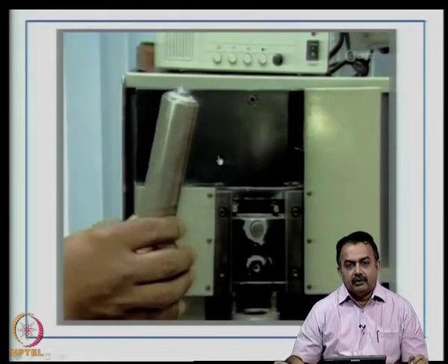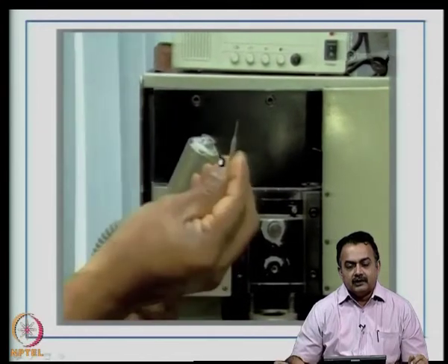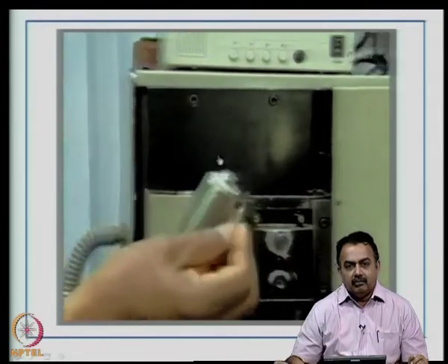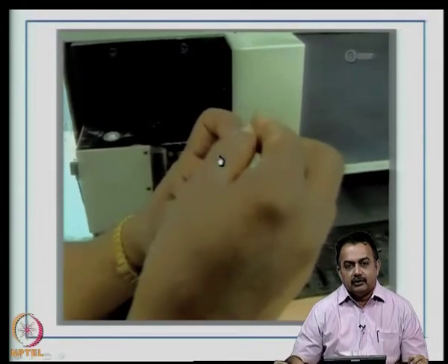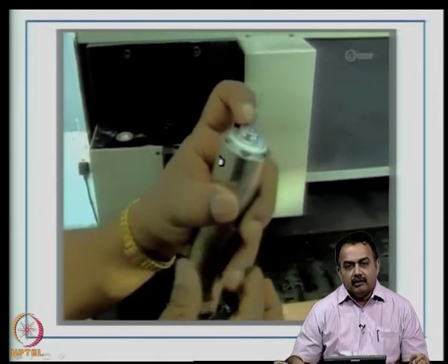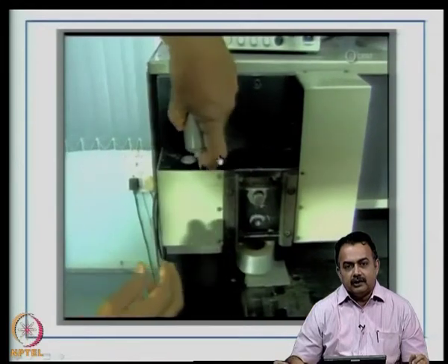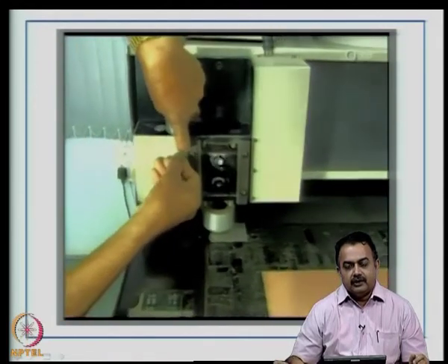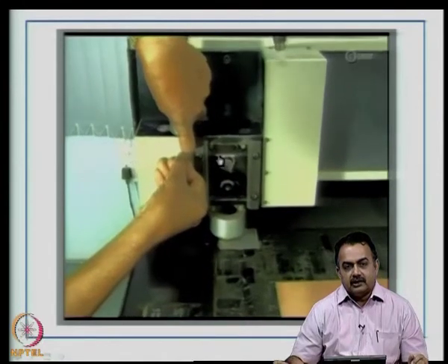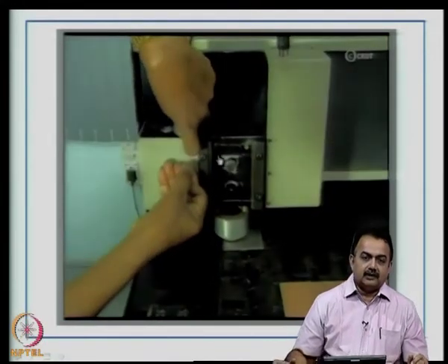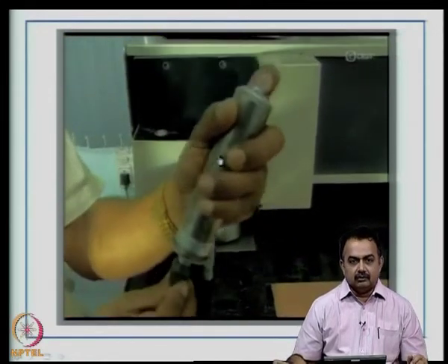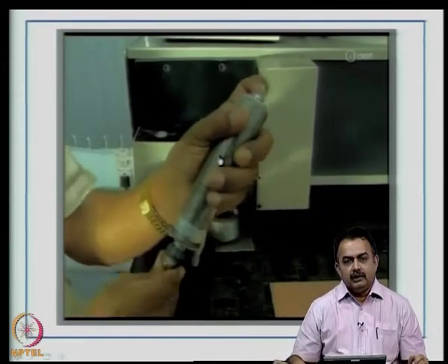Here what we are showing you is the spindle where you are mounting the drill bit. So, there are certain set procedures, especially with regard to the drill bit material protruding out of the spindle. So, here the technician is showing you what kind of distance or height is required for a stack of, let us say, 3 laminates to be drilled through and through.